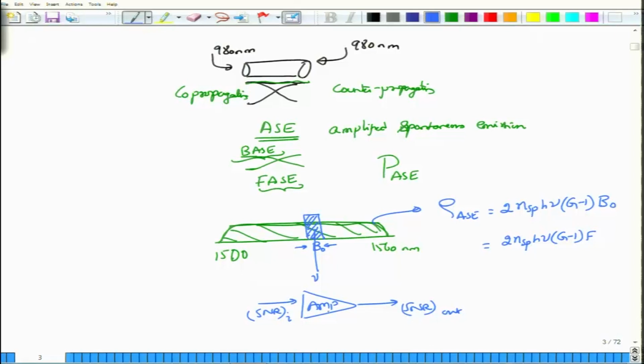Usually, because amplifiers add their own noise, the signal to noise ratio worsens, and how much it worsens is given by the noise figure or the noise factor. This is the further degradation you would expect, because most amplifiers are not ideal and they induce noise. It turns out that noise figure is a very fundamental property. It is something that cannot just be wished away, saying that I can throw this out.